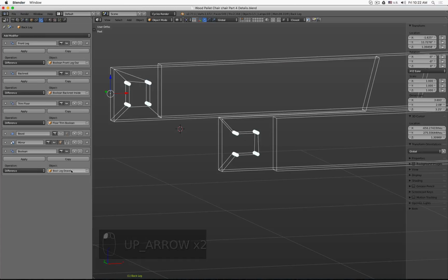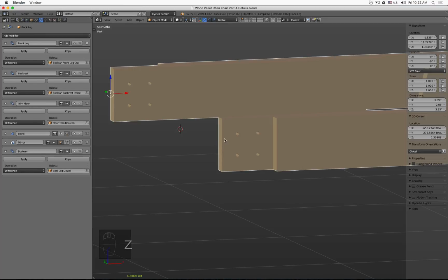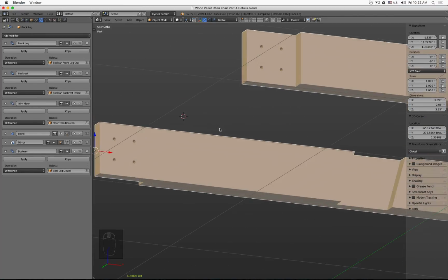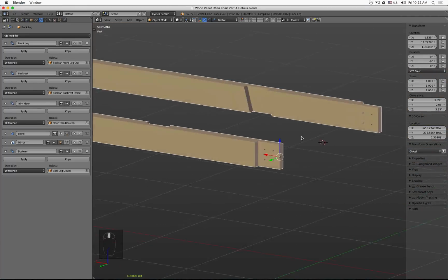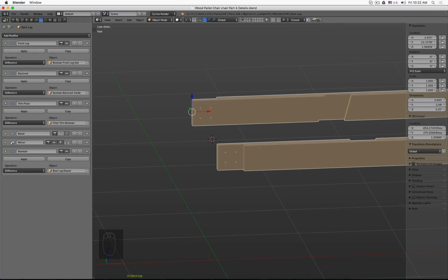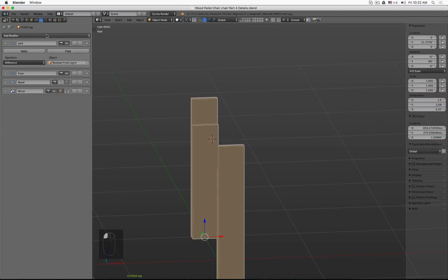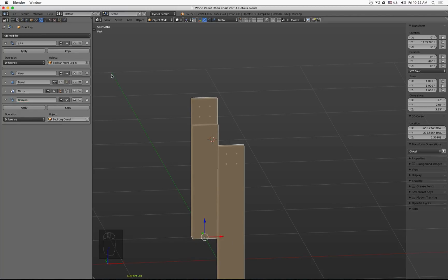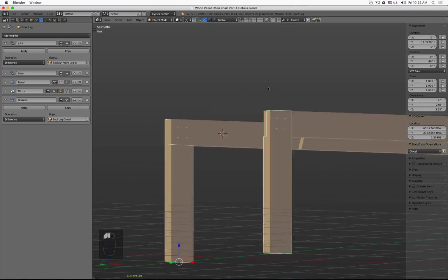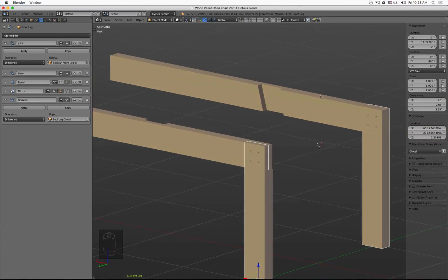I want this one. And actually it uses the result of all the, well, basically it uses the result of the 3 Boolean operations we added to it. So let's go to here. There we also add the Boolean modifier and cut this one out. And nicely you see perfectly it matches.